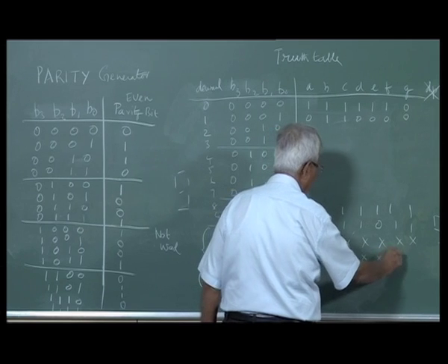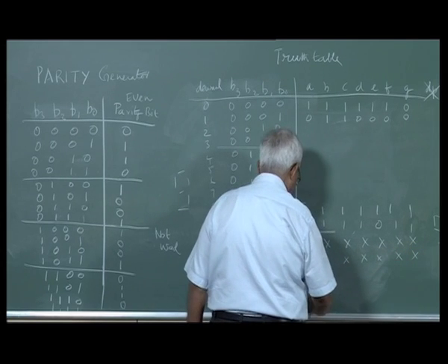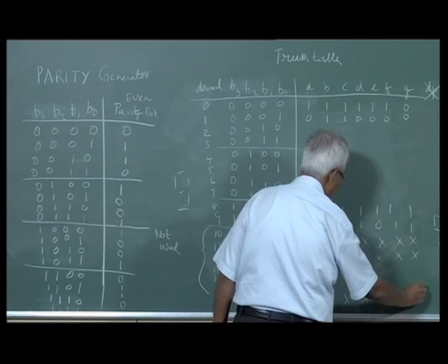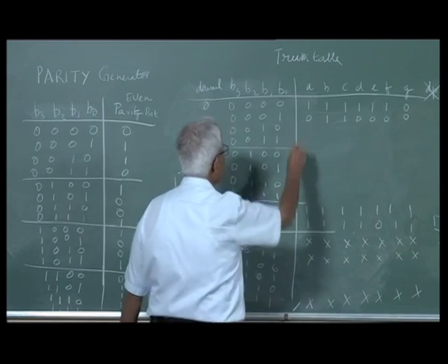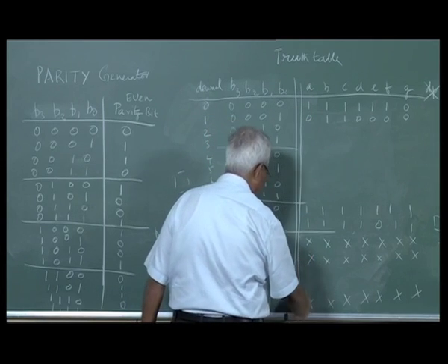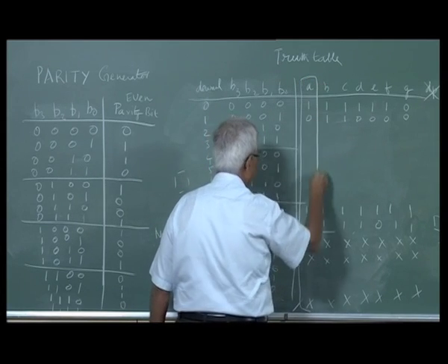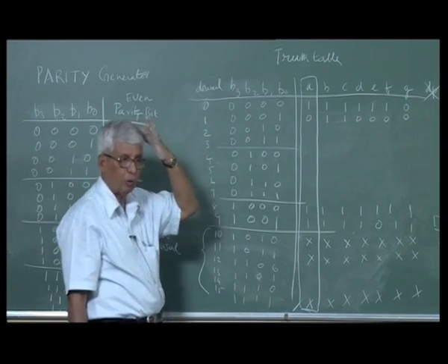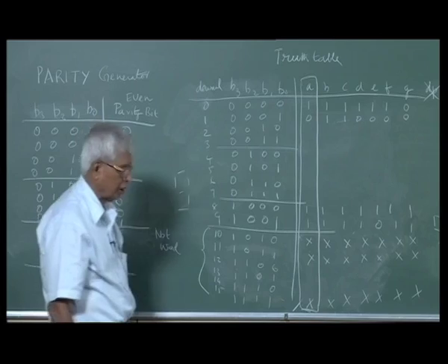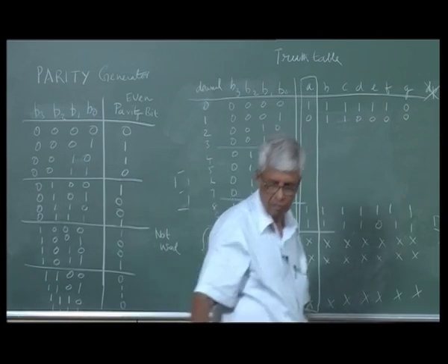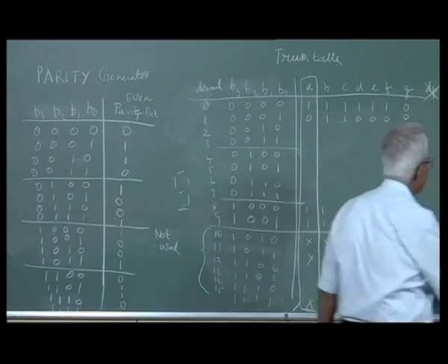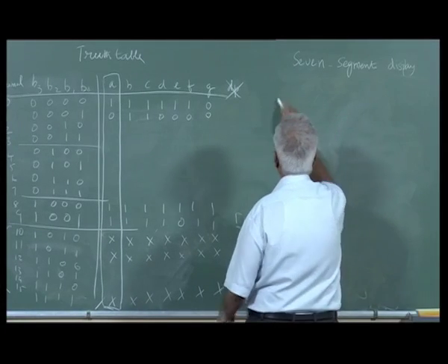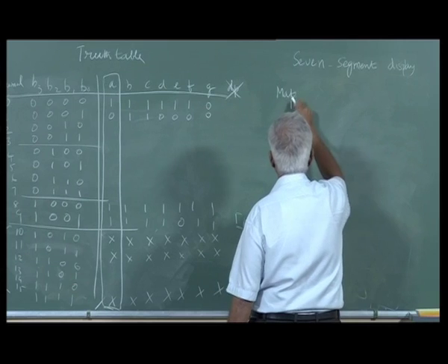Don't cares can be used to advantage in simplifying logic. We have seen that already. Now take each segment at a time. There are 4 inputs B3, B2, B1, B0 and one output A. So for example, I can draw the map for segment A.